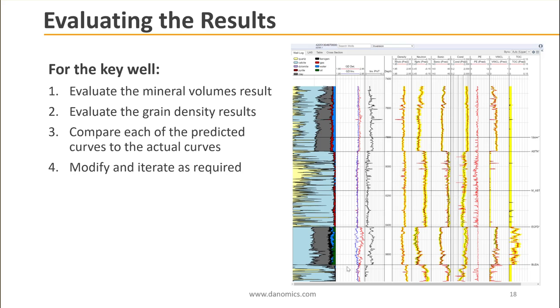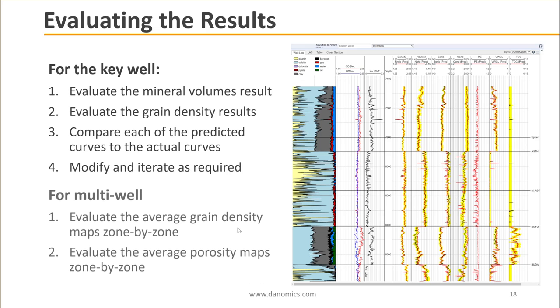Inspect the grain density results. Do those look fairly good up and down the wellbore? And then look at the predicted curves. Do your predicted curves and your actual curves match? And if not, go in and iterate and make adjustments on an as needed basis.